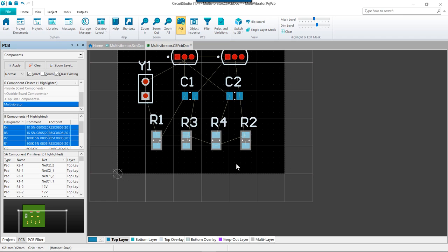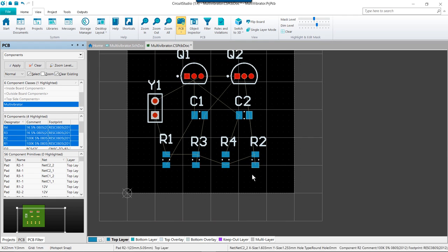If we click anywhere else within the design window, we will deselect all the resistors, and if required, you can also align capacitors and transistors, although this likely is not required since we do have a coarse snap grid at the moment. As well, even with those resistors, we easily could have aligned those with a good 1 millimeter snap grid. Just going to make some final adjustments to these parts to get the rotations correct for routing.